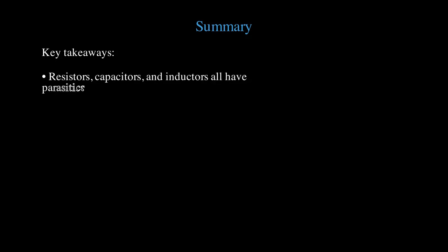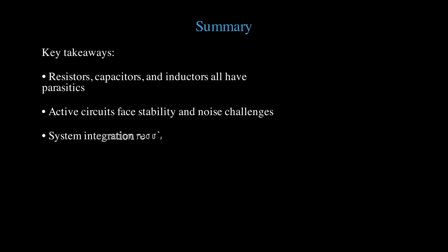Every passive component has unwanted parasitic elements that affect high-frequency behavior. Understanding and working with these parasitics is key to successful RF design. RF amplifiers, oscillators, and mixers must be carefully designed to avoid stability problems while maintaining good noise performance and linearity. Combining components into complete RF systems requires attention to impedance matching, isolation, and interference prevention to achieve optimal performance.